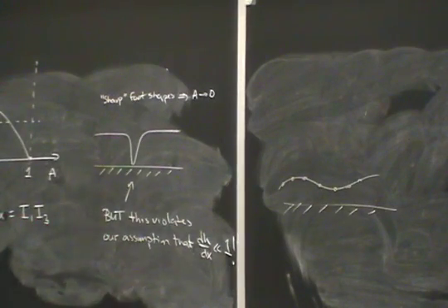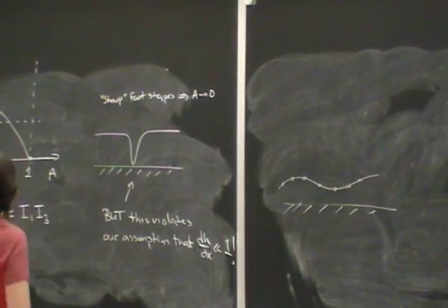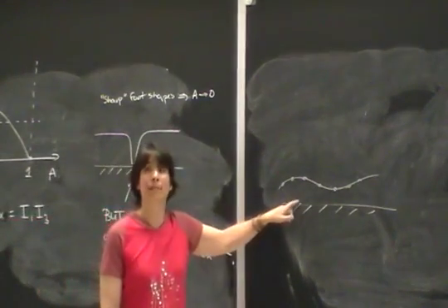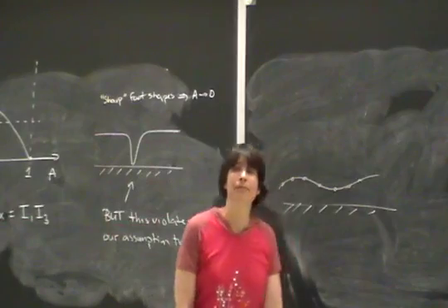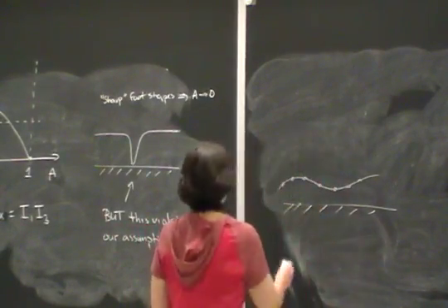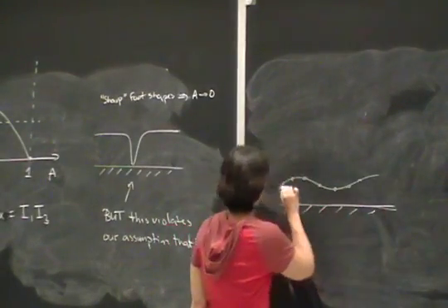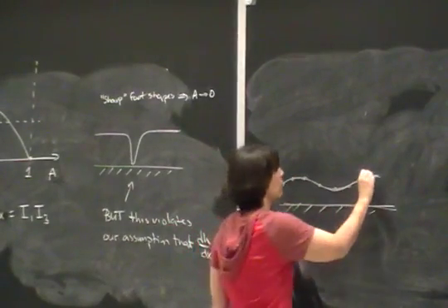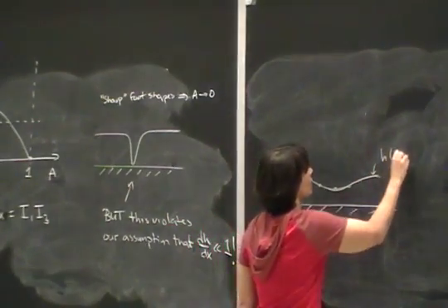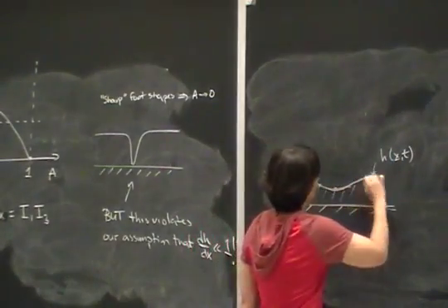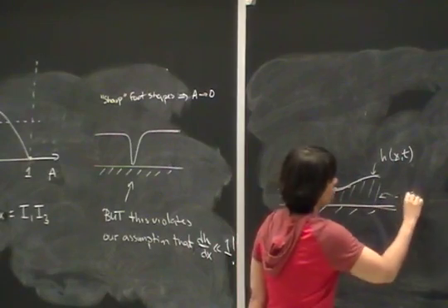Okay. So this is still the lubrication approximation? This calculation is standard lubrication approximation. Mike's calculation is not lubrication. I didn't understand what Mike's calculation is exactly. So what is it? Oh, you just solve it. So you have a membrane here, and you dictate the kinematics. So you impose the shape as a function of X and T. And then you have a fluid layer in here. And then you just solve Stokes' equations.